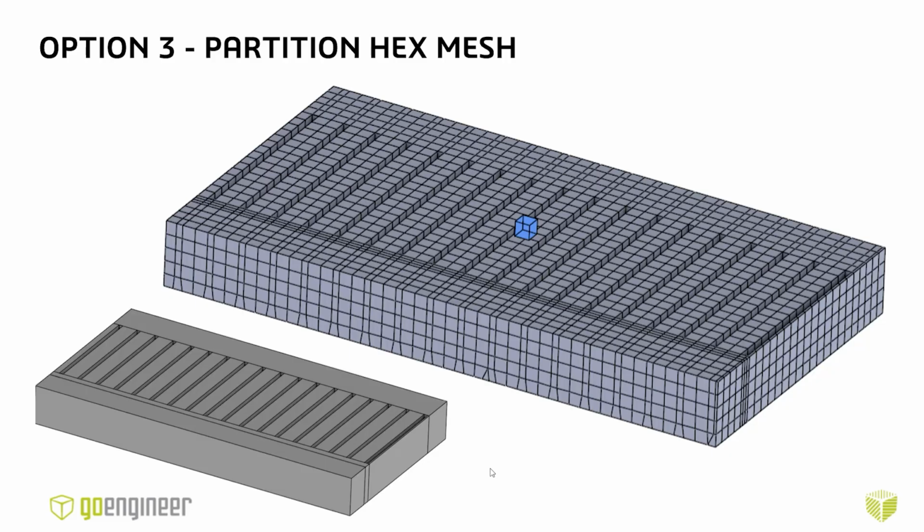So instead of using the automated meshing tools, like the control planes, the high aspect ratio elements, some of the automated meshing tools that I have, this is going to be very manual mesh creation. A lot more work on the front end to make happen. But I gain a lot of control over mesh creation. So I can create a mesh that accurately represents what's going on around these fins, but ideally create that mesh that's still very efficient to solve.